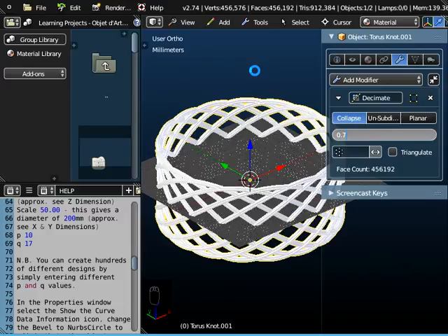And what FluidDesigner is doing is it's combining some adjacent faces together into one. So it's taking two faces and joining them together and creating it as one. So you can see the face count has gone down now. Now when you reduce the face count, you'll reduce the file size. And the amount that you've got to do this will just depend upon the final file size of the object and what the limitations are at the company that's going to print the object for you.